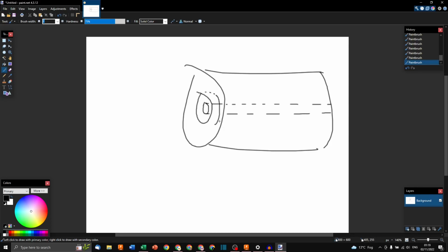And then inside of here, I want to have a hollow bore in which I can put a bearing, and a hollow bore here in which I can also put a bearing. These are actually called bearing seats because you take a ball bearing, that's a ball bearing, drawn with a mouse, and you can press it into the bearing seat, and so it sits the bearing in the bearing seat. So that's a wheel, by the way. So today we'll be creating a wheel with two bearing seats.